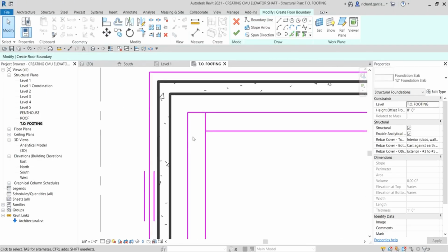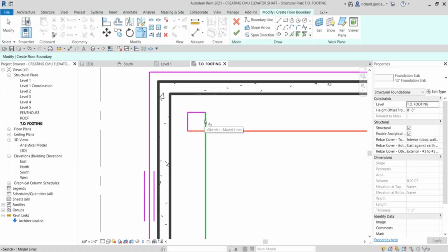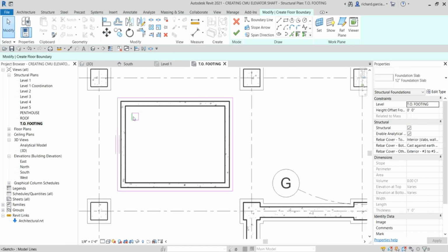And then we need to create an opening here. So we need to close this. Make sure the opening here is just a square. So we will be using trim extend to corner to clean it up. I'm going to select that, and I click the two sides that you want to remain. So you select that, then select this one, and then select this one. All right, so there's now our opening. That's, for example, for our sump pit.